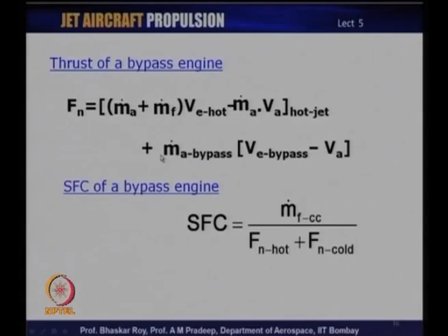So, in the second thrust producing component here, the mass of air that is being activated through the bypass system, or bypass cold jet, is indeed very high, and that is what produces a very high cold thrust from the second component. Whereas, in the first component, as we know, it is the V E hot which is the most important aspect of thrust production, because the mass flow there being processed is not of very high order.